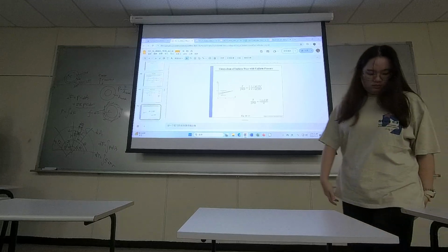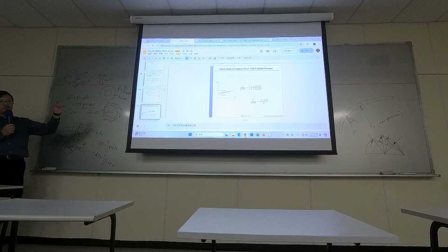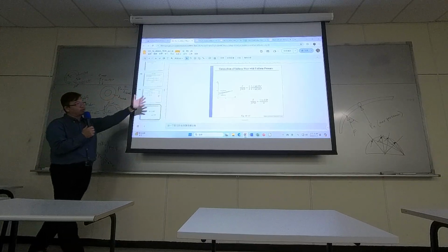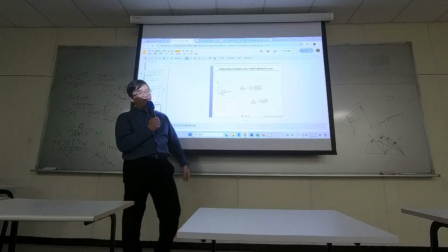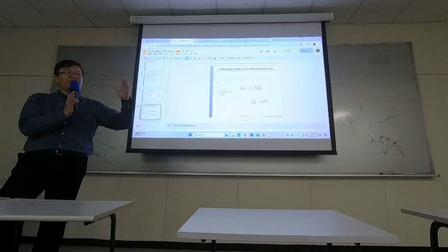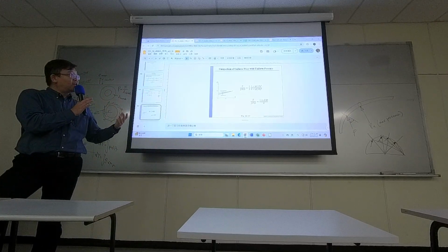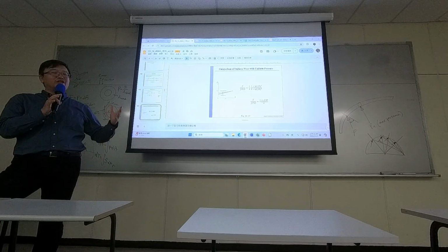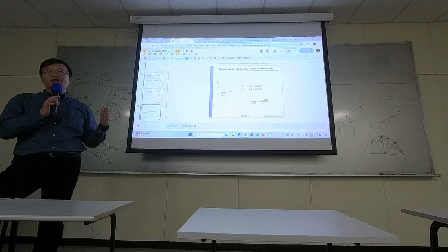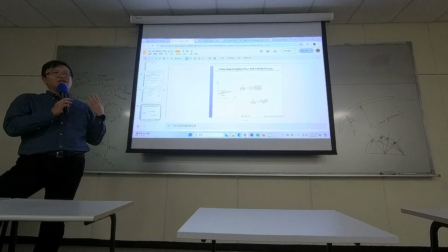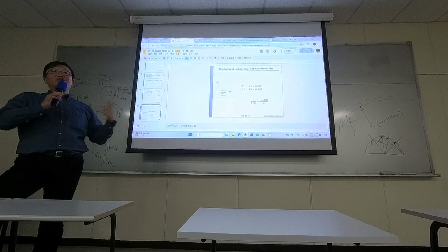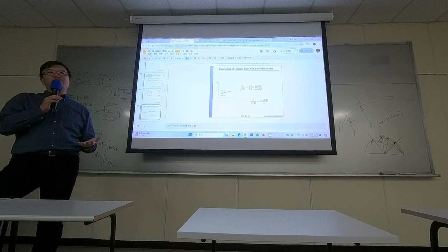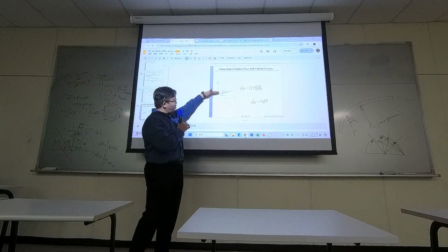So when you compare them, you realize that if the ring geometry is very thin, then there's no big difference between the uniform pressure and uniform wear models. But if you have a thick ring, then these two are the two extreme cases, whether you assume the wear is constant everywhere or the pressure is constant everywhere. And I believe in reality, the wear is not uniform anywhere and the pressure is not uniform anywhere. So the reality is somewhere in between.